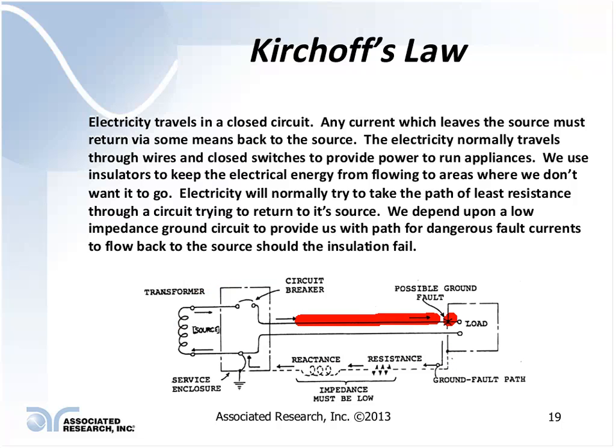But what happens if this ground circuit is not there? If that ground circuit is not there, my current still flows into my product, and now my whole chassis will become energized. And this is going to be at whatever potential is coming out of this transformer feeding power into this. With this ground circuit not being present, a fault could occur here as long as that insulation is not shorted to the neutral side of the line.